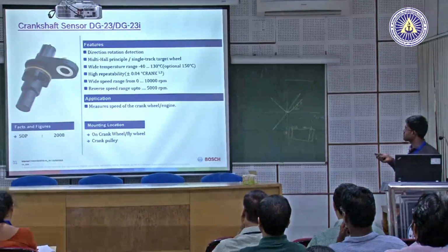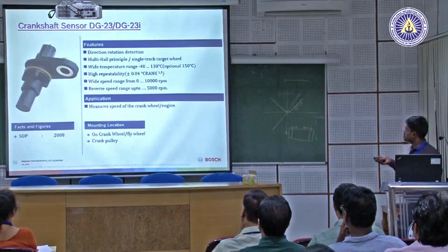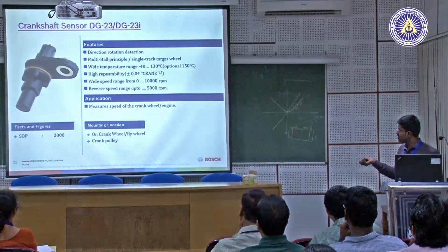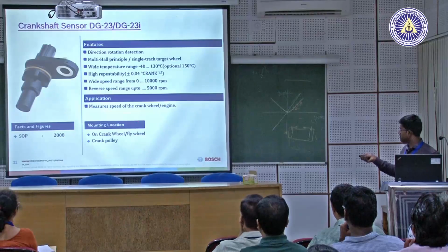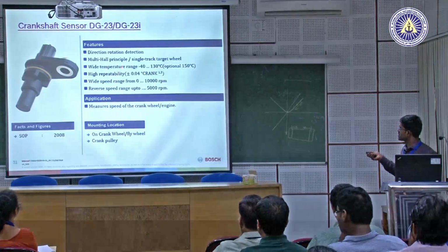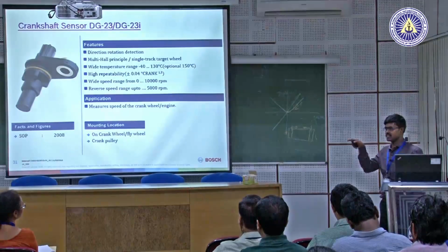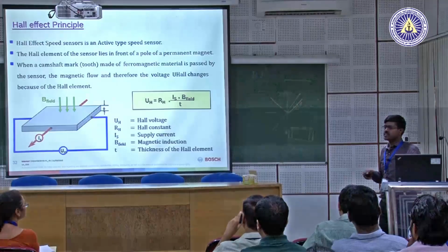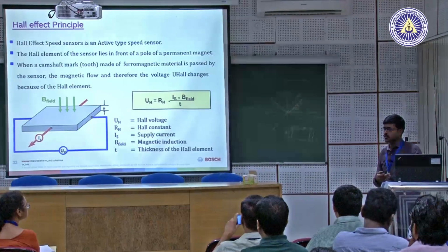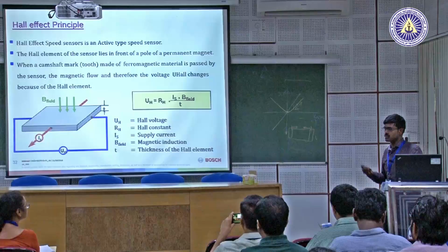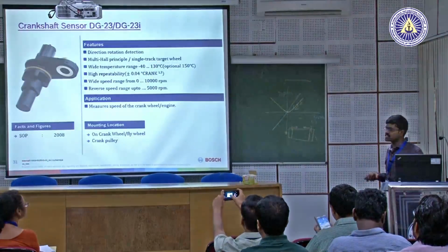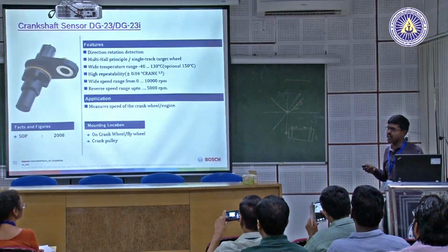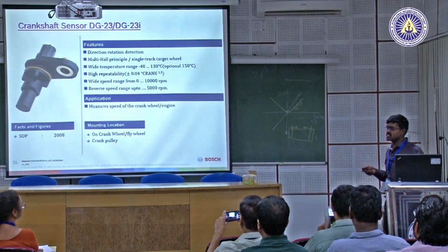We have one more sensor which is a digital sensor. The function of this sensor is also similar to what we have seen in the analog sensor, the same mounting, the same application, but here the output will be in terms of a digital signal. It is based on the efficiency you require for your ECU to calculate and analyze. The digital sensor always has higher accuracy and better tolerances when compared to analog. So, again, cost is a matter for customers.